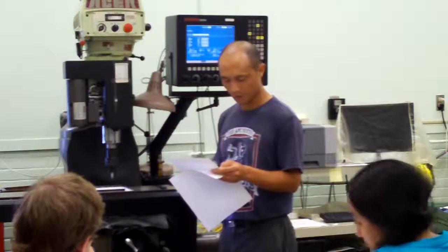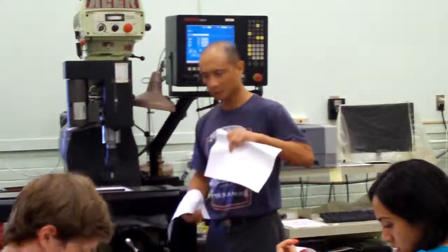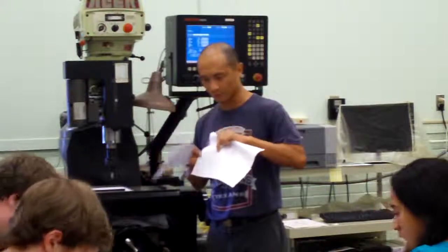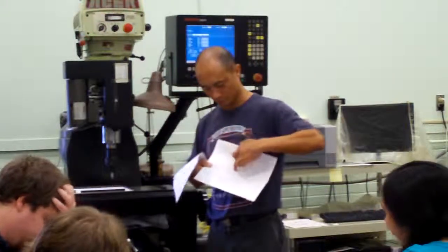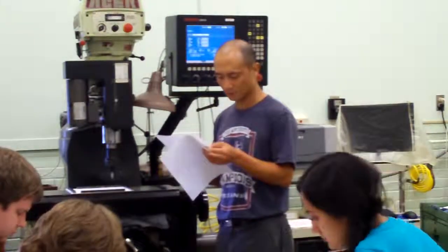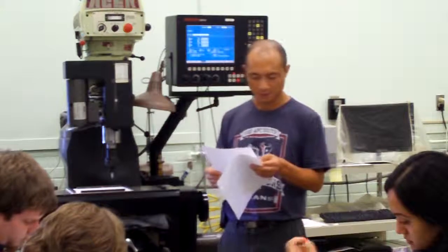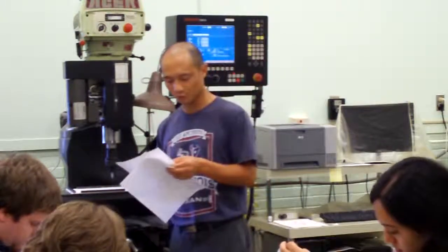Let's go to N75. At N75, we were at the lower top left corner of the house. Now N75 makes you draw a straight line to X3, because the Y is not changing, so we are moving along the X-axis alone. N80 is G0. We lift up the pen again, and then we move to X 1.75, Y 2.25.